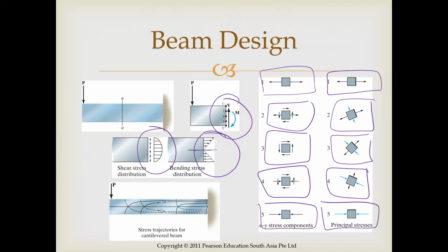So when we design our beams, we calculate the maximum stress at the top and the bottom. Because those are the maximum principal stress that's going to occur anywhere in the beam, that's why we directly use that for our design. I mean, in theory, what you need to know is what is the principal stresses and the absolute maximum shear stresses in this object, and that's what you should be designing for.